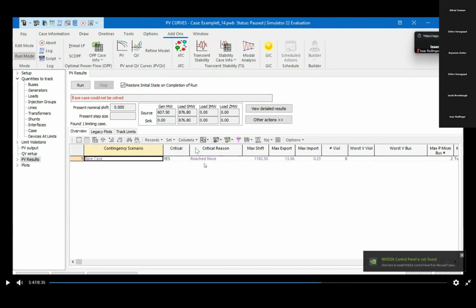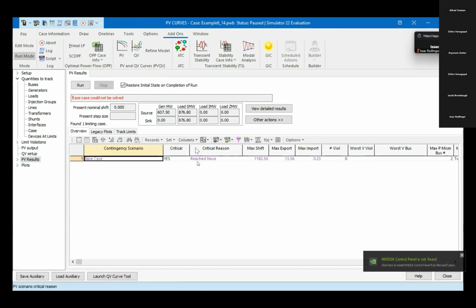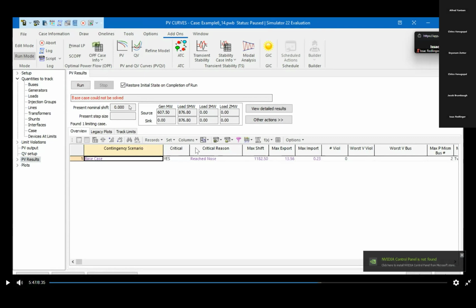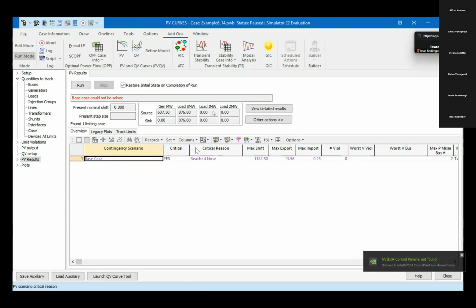Here, once it reaches the maximum point, meaning it has reached the maximum number of iterations, the iterations are complete and the results are very similar between the previous iteration and the current iteration. It will say the base case cannot be solved after that point. It doesn't mean the complete base case is not solved. But if an error comes up and the base case cannot be solved at the beginning itself, then the system will not run here. When I ran the test simulations, it never solved. It just continued trying to solve it, so I think that's why my graphs came out funny.